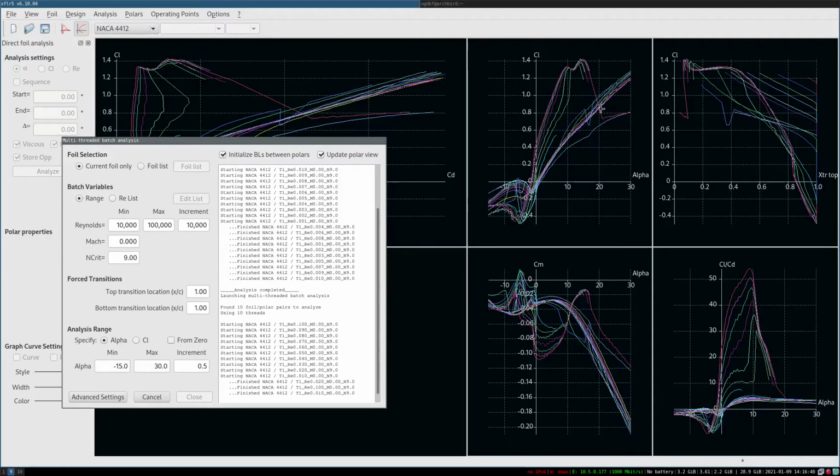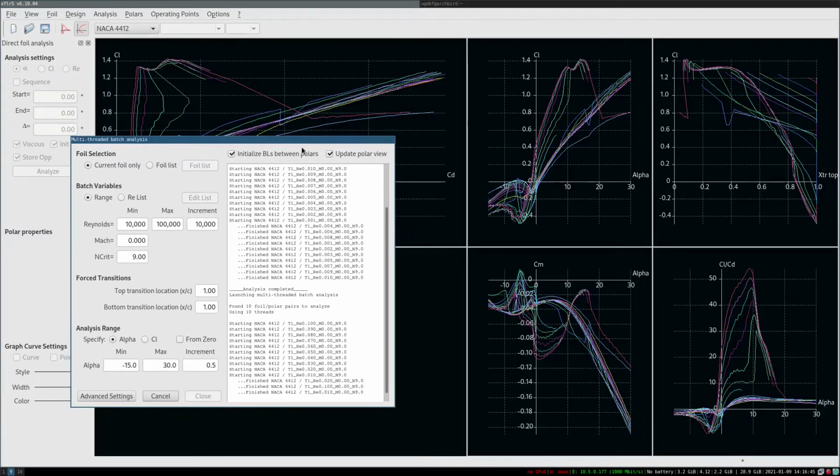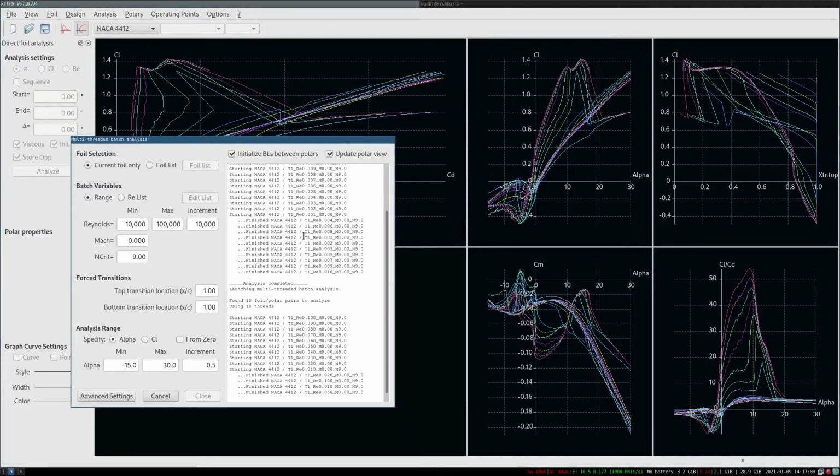But if you get a straight line like this, sometimes it means that there's a point here and there's a point down here and it's interpolated everything in between. Large gaps like that can mean you need to go back to the airfoil page, to direct foil design, and refine the airfoil globally, locally, or in some cases, if you have some really broken geometry, spline over the airfoil shape that you have from the DAT file, re-export that, and then try again.